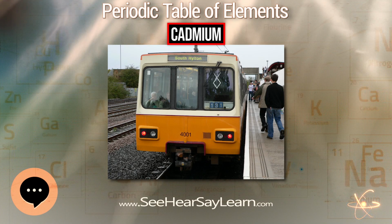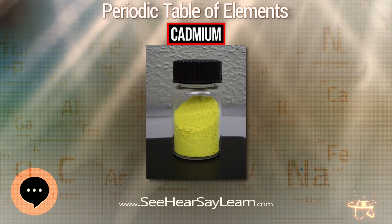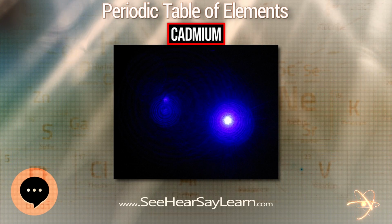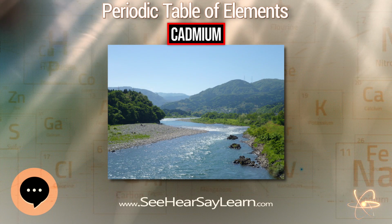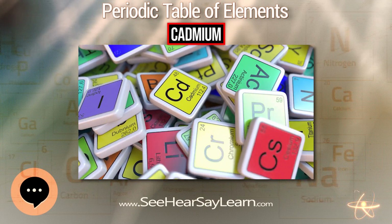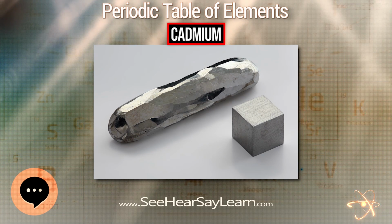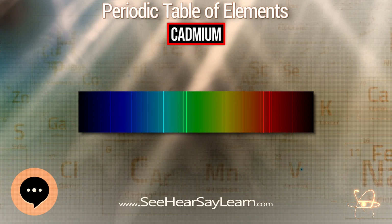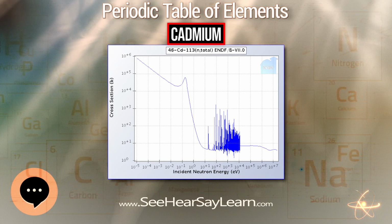Cadmium electroplating, consuming 6% of the global production, is used in the aircraft industry to reduce corrosion of steel components. This coating is passivated by chromate salts. A limitation of cadmium plating is hydrogen embrittlement of high-strength steels from the electroplating process. Therefore, steel parts heat-treated to tensile strength above 1300 MPa should be coated by an alternative method. Titanium embrittlement from cadmium-plated tool residues resulted in banishment of those tools in the A-12/SR-71, U-2, and subsequent aircraft programs that use titanium.